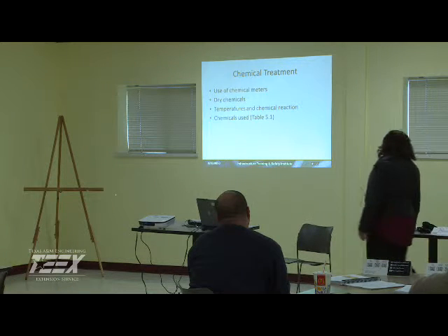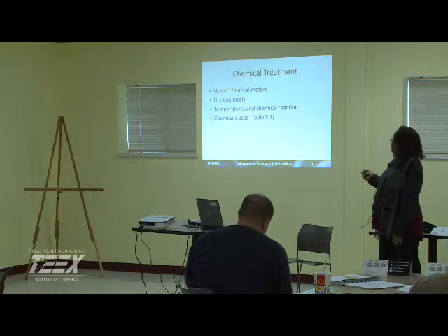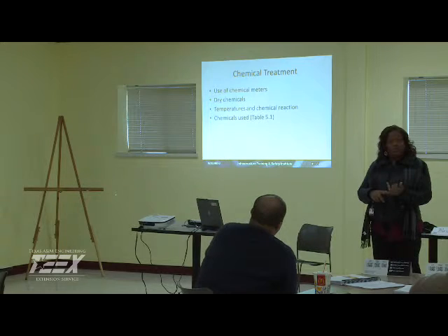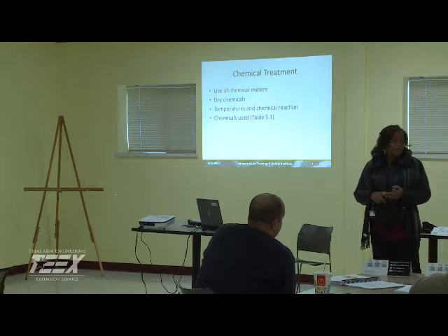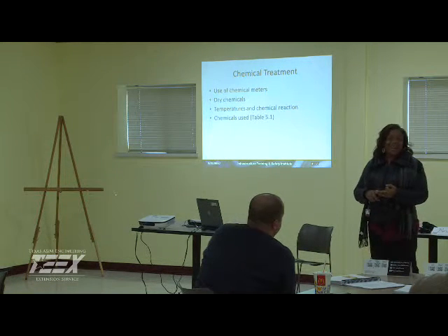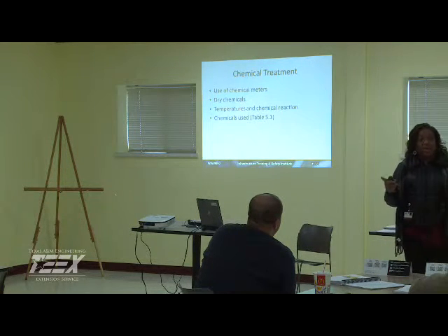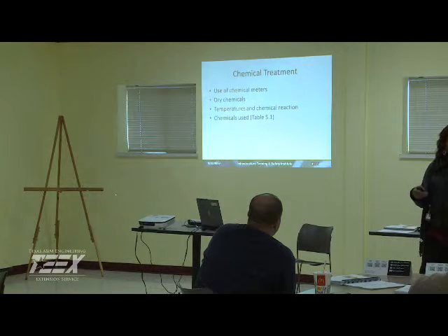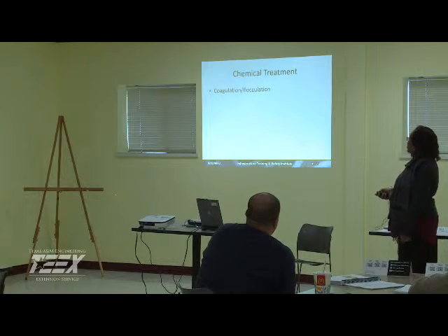So some of the chemicals that we use in chemical treatment are listed. Can you think of any of them that you use? Alum, I know, is one that we use. What's another one? Polymers, very good. And I think I heard you say something that raised the pH earlier. Lime, soda ash, polyphosphate. Ferric chloride, yes. A lot of chemicals that we use on the water side in order to enhance our treatment process.